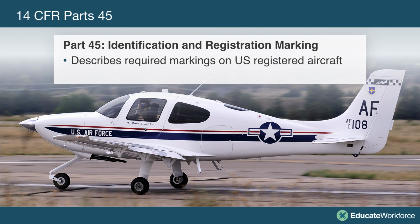If the part has a specific replacement time, if it is a time-limited part, we need to determine what the inspection intervals are. We need to have a related procedure or specification to maintain that particular part. We either need to have it added to the maintenance manual, or we have to have an instruction for continued airworthiness, an ICA, associated with the part and the serial number for each specific part.